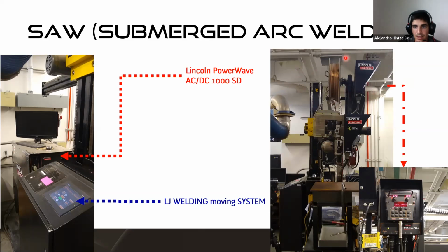Instead we have fluxes, so the weld will be covered in flux, and technically you don't need to protect your eyes, because there shouldn't be any arc exposed. But it's still good to take all the PPE and precautions, because if the weld goes wrong, the arc might be exposed, and you might want to be protected anyways.